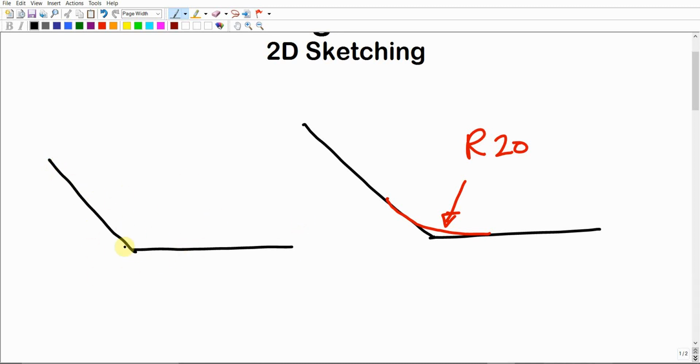Then I need to draw the curve. First of all, in the beginning, you have to draw two lines. One line is parallel to the first line, with a normal distance equal to the radius of the curve. How much is the radius of the curve? It is 20. So what you're gonna do is draw a very light vertical line, using the set square,